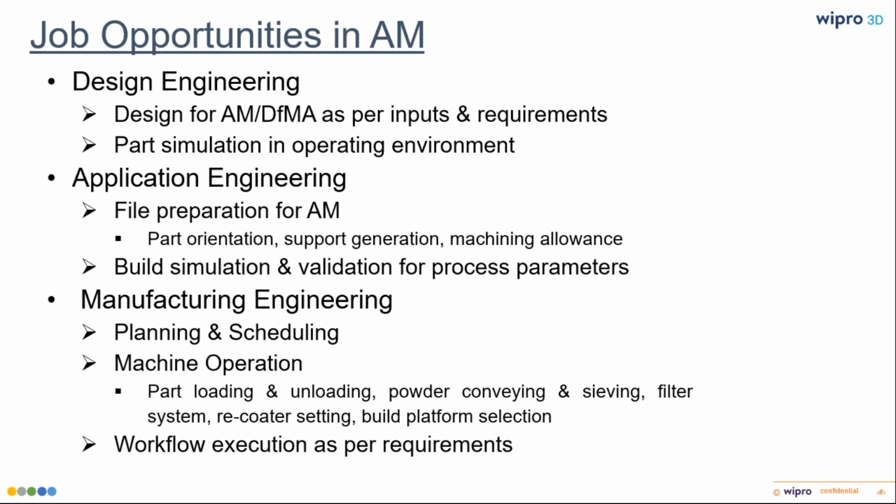These machines are operating, they do not require an operator as such, but when you're working with consecutive builds, you do need to plan your activities in such a way that your builds do not accommodate a lead time, and you need to identify what build should go on first, and a sequential flow as to which builds should be catered for. And once the part is fitted in the machine, you do need to think about the loading of the part, the loading of the powder, conveying and sieving after the build is over, and the filter system. Because these machines work with filters, you do need to think about after how many builds you would want to replace this filter.